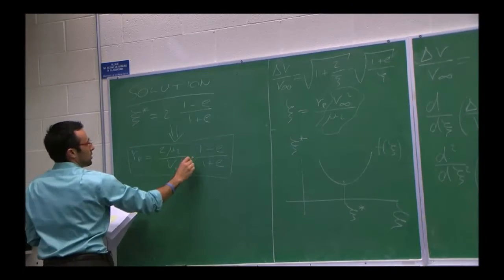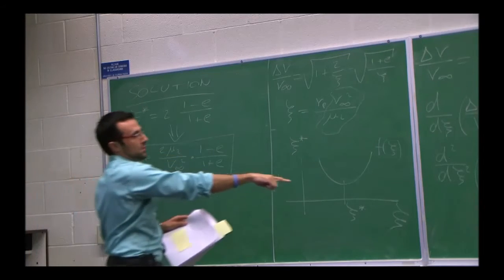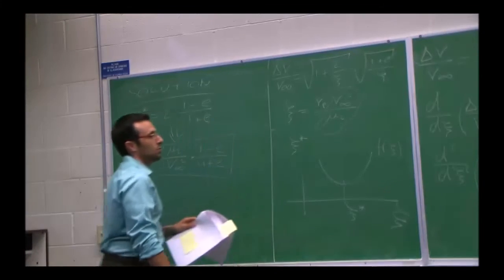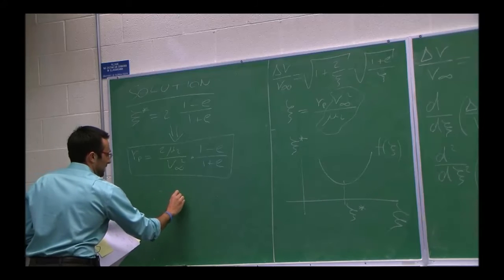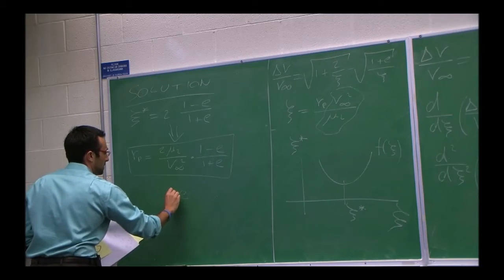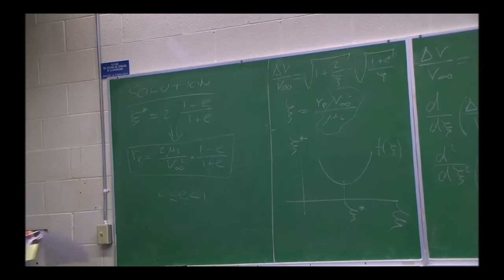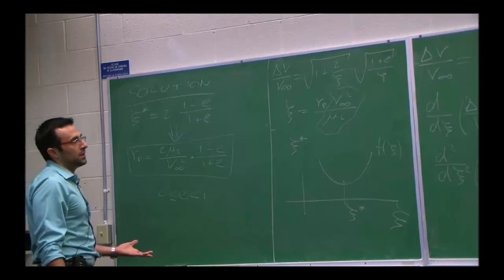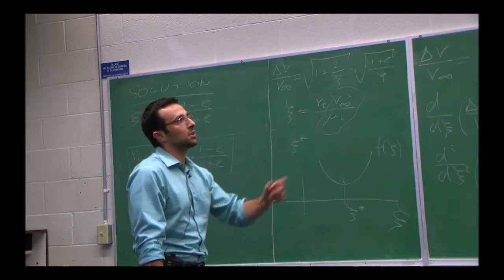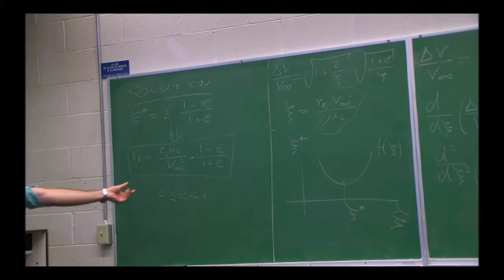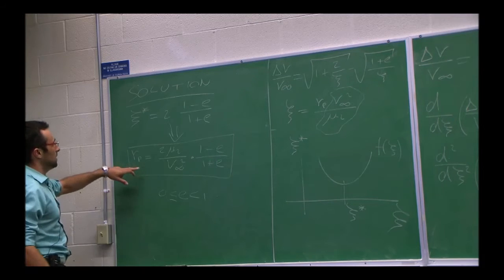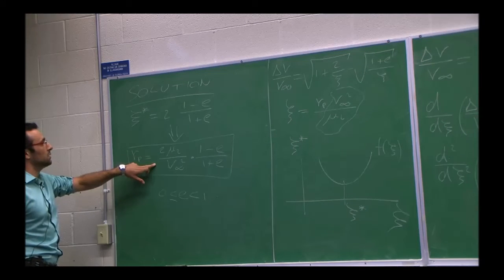And also, to make sure that this condition is respected, it comes down to saying that the eccentricity of that capture orbit has to be between 0 and 1, 0 included. So that's one thing you may want to do. If you want to go into an orbit around the planet, do it in an intelligent way. Going to the circular orbit is not necessarily the best. It's actually an orbit that respects this condition.